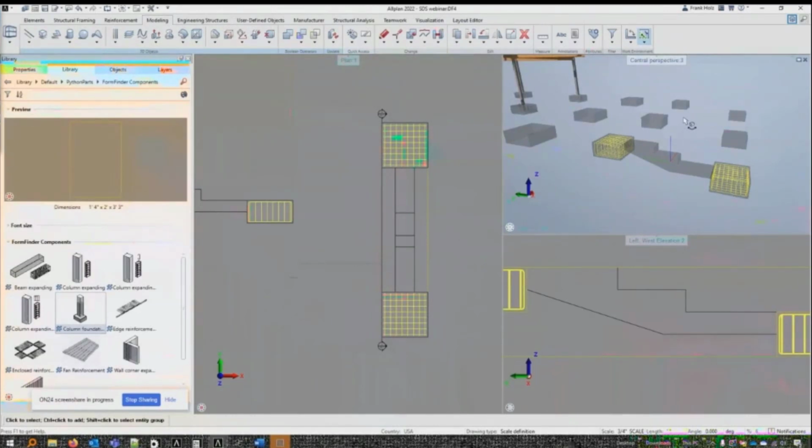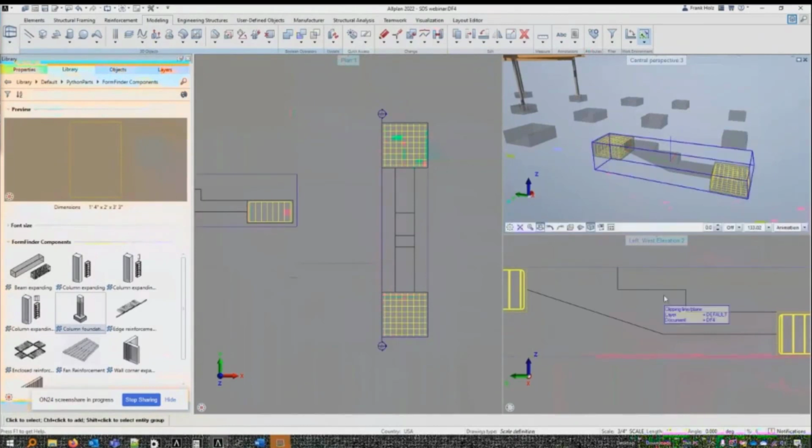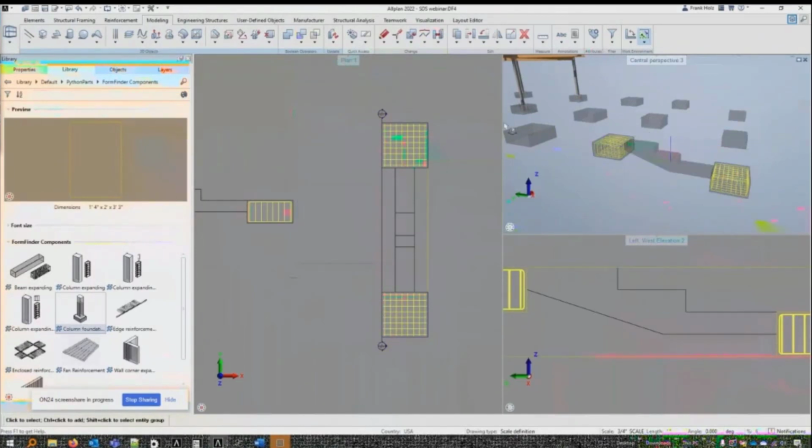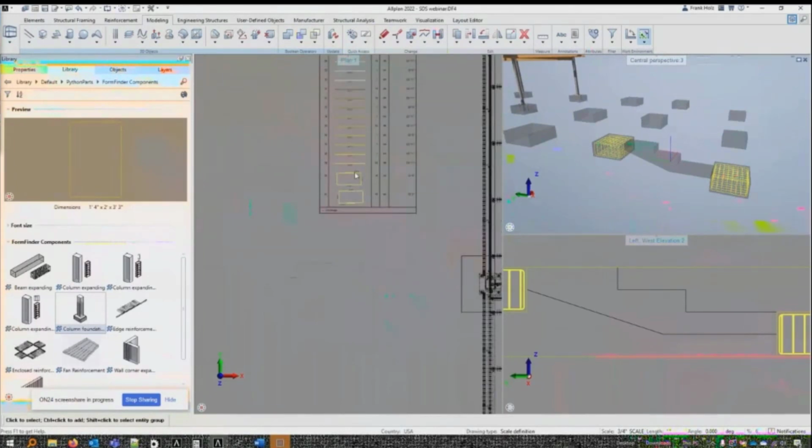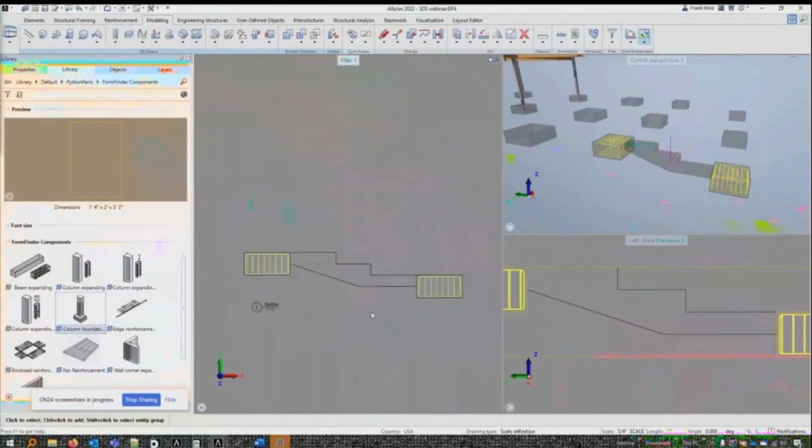They're able to work in the way that they always have. And with an extra click or two, they're getting a whole lot more information out of the back of it. And because it's a 3D model, you're going to see all that stuff is constantly in sync. Every time I make a change, it's going to update my schedules, right? So the 2 bars I just added here now show up in my schedule back up by the wall. The sections themselves automatically update.